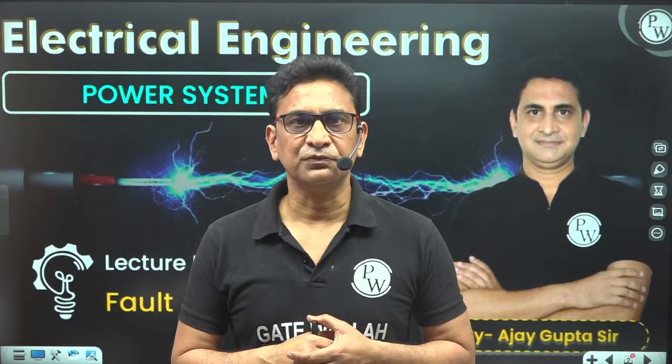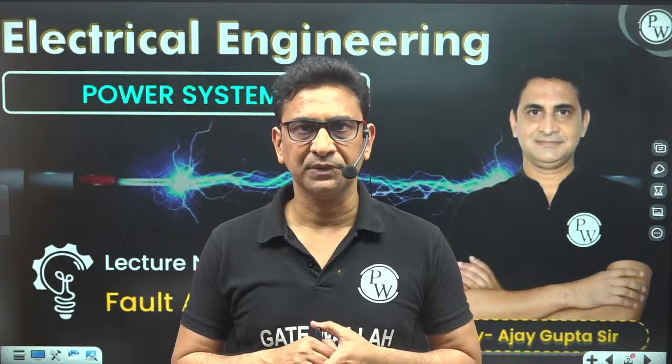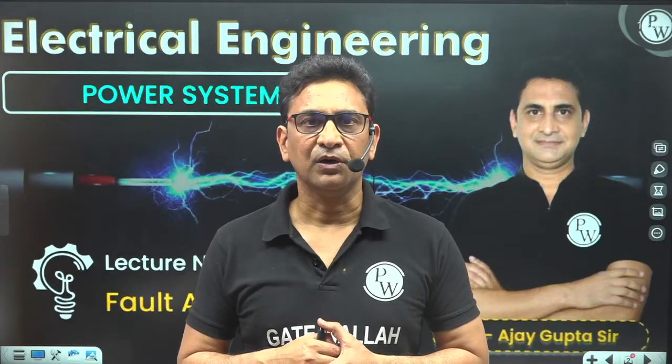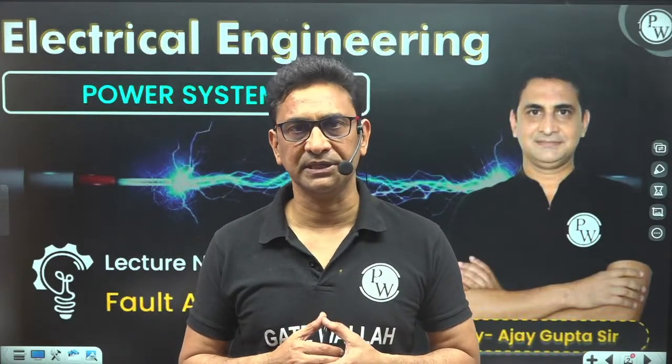Now we are discussing the unsymmetrical fault. An unsymmetrical fault is a fault which involves either one phase or two phases. The first fault we are discussing is the line to ground fault. In the line to ground fault, one phase is short circuited to the ground. I told you whenever a line to ground fault occurs, all three, that means the positive sequence, zero sequence and negative sequence currents, come into the picture.